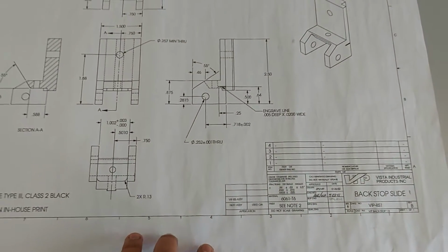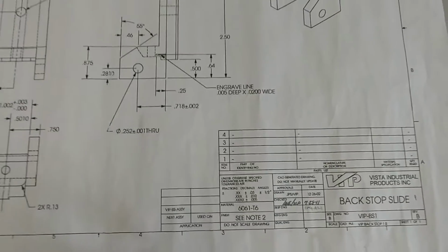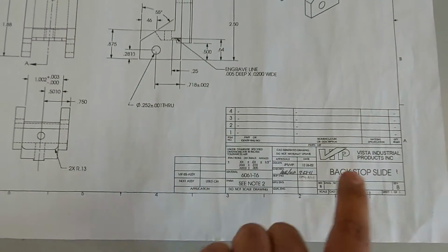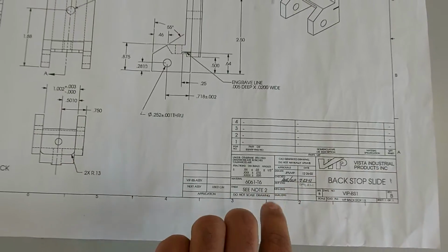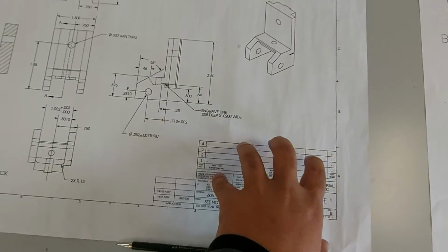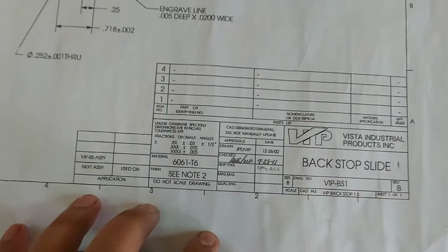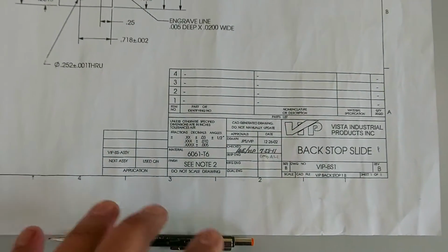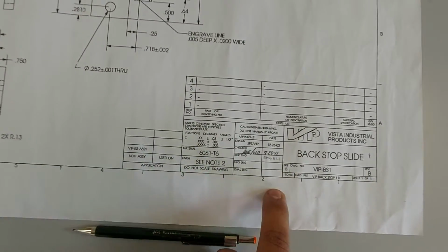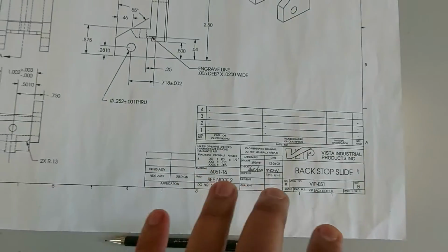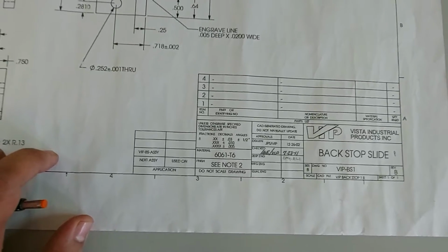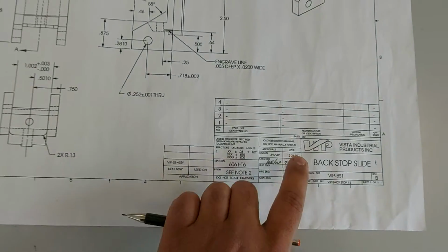Okay, the next and most important component in the drawing is the title block. The title block is a massive component of a blueprint after the engineering drawing. After the engineering drawing, this is the biggest part in the technical drawing, where mostly the majority of the information is available. Contractor, client information, who is the client, who is the contractor, what is the name of the part, what is the name of the company, who is responsible, tolerances, material, finish, each and every detail will be in the title block.